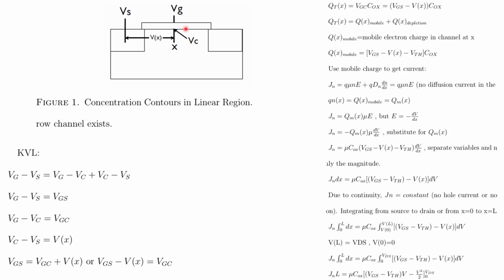So Q is equal to V into C. VGC is the voltage that we are applying, and let's suppose the capacitance of your SiO2 layer is COX, right? Now we replace the value of VGC from here, VGS minus Vx, and you will get the total charge which will accumulate in the inversion layer, right? Also, the total current is due to drift plus diffusion, but the amount of diffusion is very less here, so directly you can consider the drift, right?